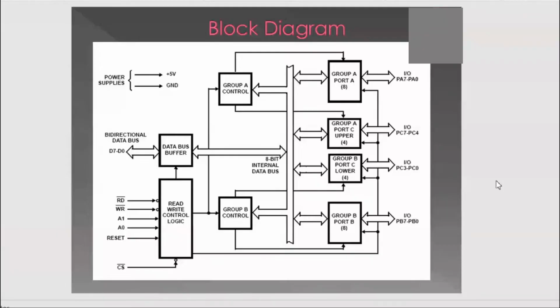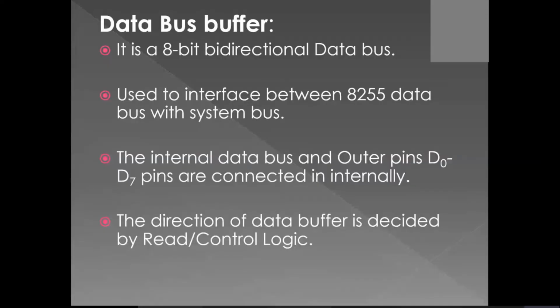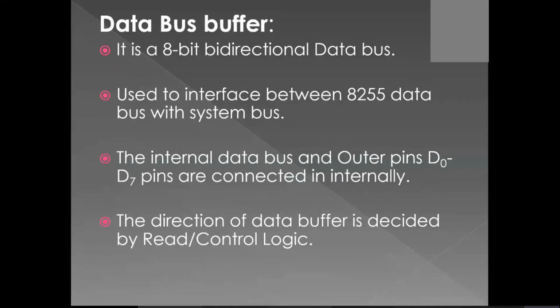So till block diagram we have already studied in the last class. I told you that every interfacing IC will be having something which is called control register inside, CR. Fine. So today we'll study about the control register. The control registers are basically of two types, or you can say there are two configurations of control register. Fine. So let's see what is inside 8255.